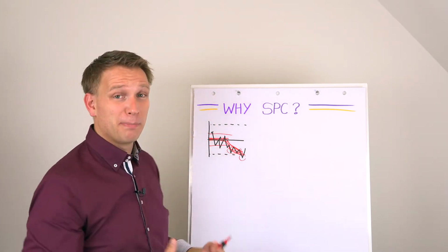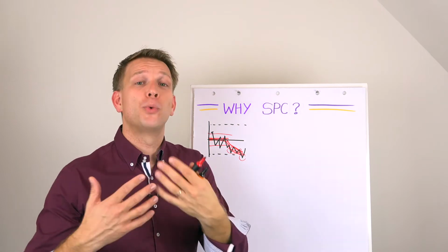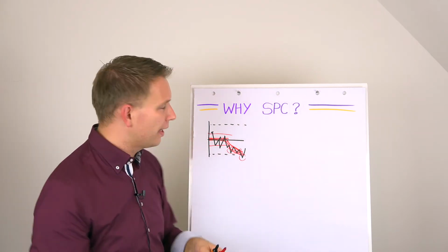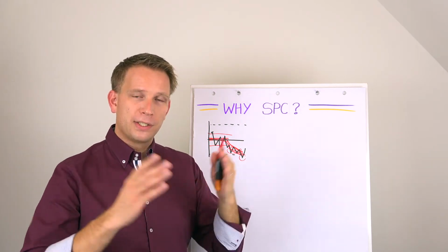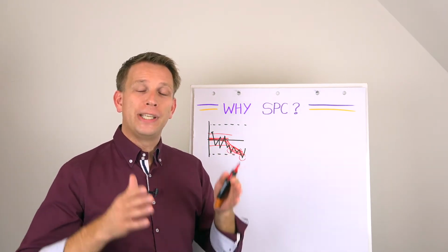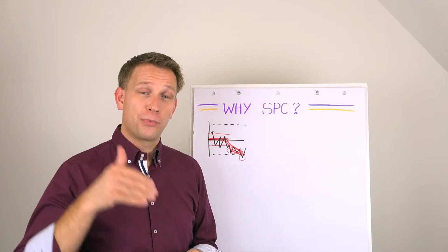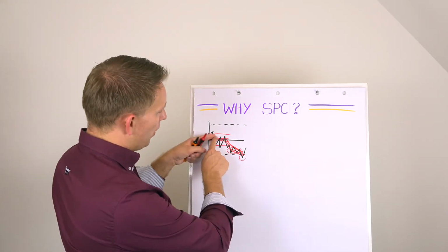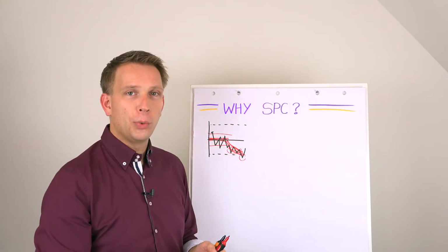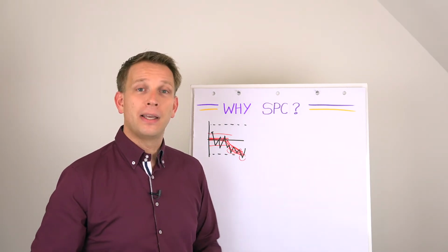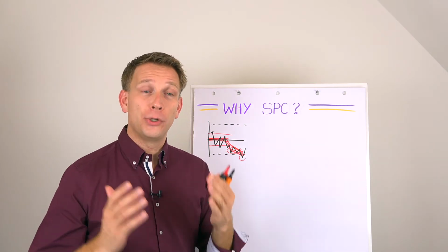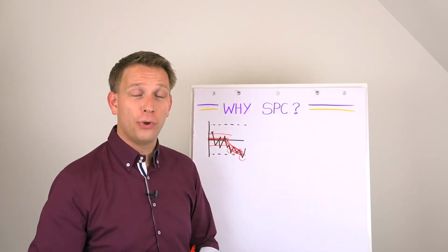These control limits become very wide, maybe too wide for your liking, but they become wide because these control limits are the 3 sigmas based on the historical data of this process. So when it goes a certain way, you know that there was a shift in how the process is behaving. And that is what we do with statistical process control.